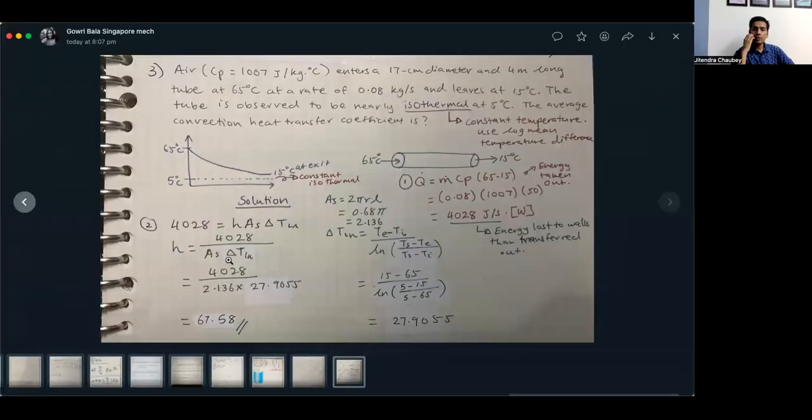Okay, I hope you understood how to find the delta T, right? Log mean temperature difference. Yeah, I do. I understand that. No problem. Okay, see, it will get very difficult for you if you simply go through the solution. You should understand how to write it down yourself. Every question will have a different situation. Like in this case, the graph is in such a way. In some questions, the graph might change. Like you might have a horizontal graph upward and a fluid going like this. Even in that case, just take delta T1 over here and delta T2 over here. You will never go wrong.